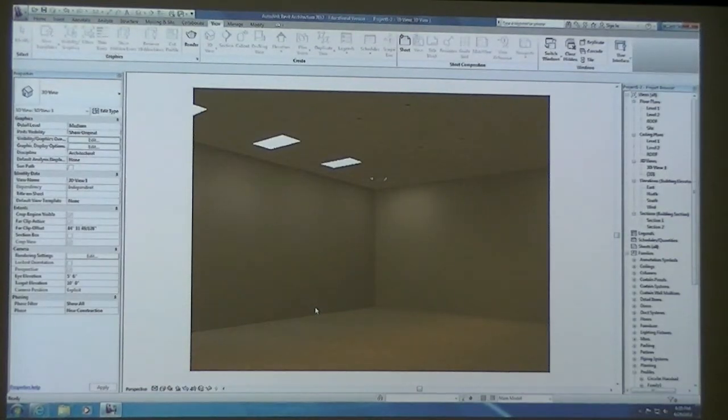And once you get the model to a certain level of detail, you're cutting your sections up and putting them on a piece of paper, and then you're adding 2D elements on top of your model once you've got your model settled, in order to actually detail it out. If you're looking at a wall section through CMU, you're going to be able to draw a 2D CMU block on top of your model, showing what the CMU looks like in section, because Revit's not going to model that level of detail. It's just going to show you a hatch pattern that's associated with it. But I can show you guys some examples.